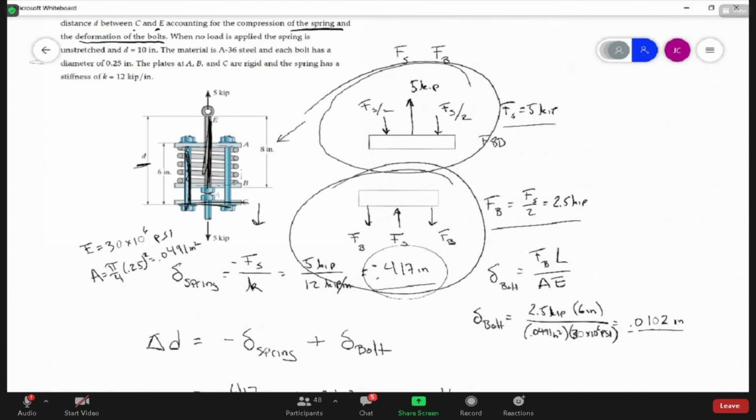It comes out purely from the free body diagrams. That allows you to figure out the stretch in the spring and the elongation of the bolts. Then, how do we combine those elongations geometrically to give you D? You can use this thought experiment in a lot of things, where you hold one factor fixed and see how the quantity you want changes with respect to the other factor, and then flip it. Then you can figure out whether they add or subtract easily, okay?